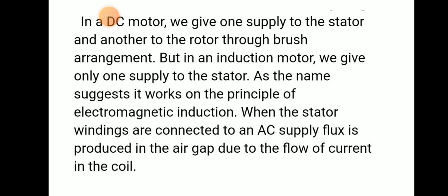Here what is happening is, in a DC motor there will be one stator and rotor, and through a brush arrangement it will work. But in the induction motor, we give supply to only the stator. So, by the principle of electromagnetic induction, when the stator windings are connected to AC supply, flux will be produced within the air gap, due to the flow of current in the coil.